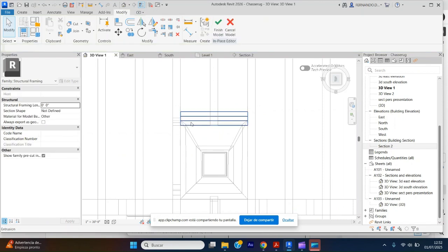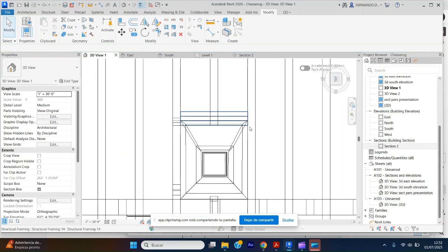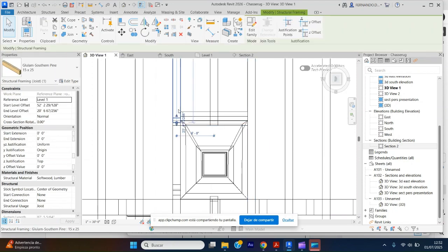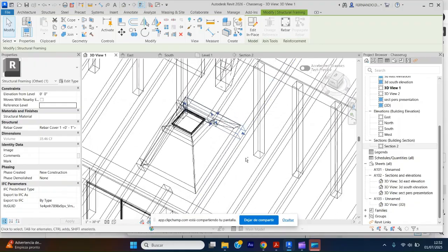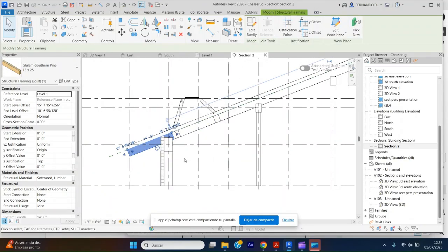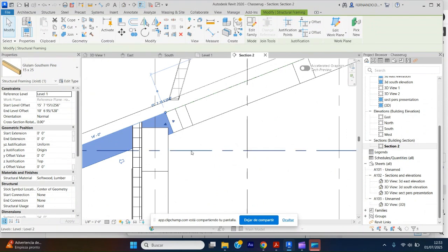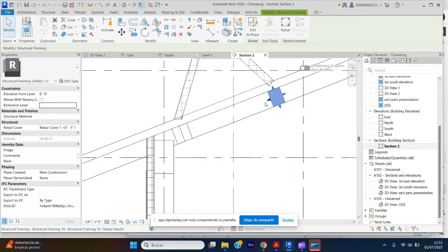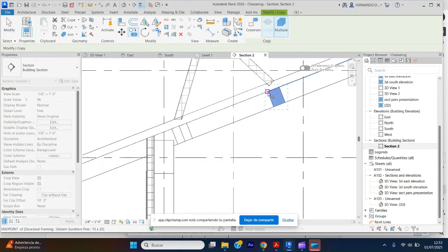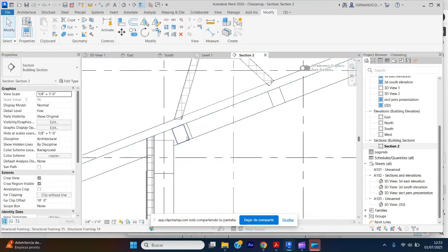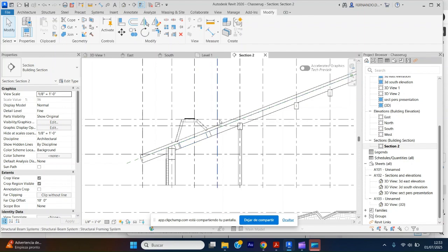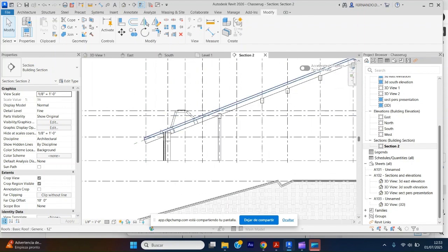Okay, so all around the skylight, the new skylight, we need solid elements. We have this beam here, this beam there, and we need this element there. So this is what happened in this section 2. Okay, so probably I can copy this element here, and now I have the solid element. This wall will be resting here. And are we done? We're not done.